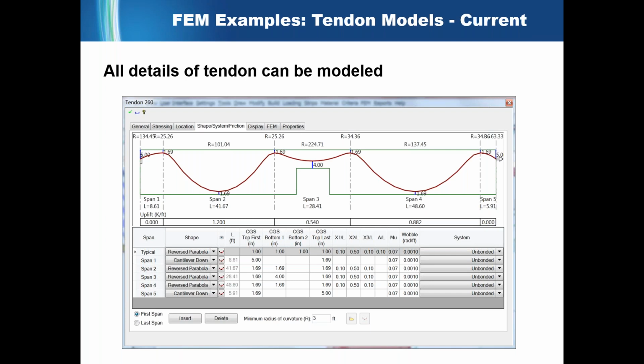Another thing to note is that the way we specify, or lay out, tendons is with a CG offset from your extreme fibers at the top and bottom at mid-span. In a case like this, it's really nice if your slab section or beam section changes thickness, which of course happens over the course of your project design, that the intention of your profile will be maintained even as the slab section or beam section changes.